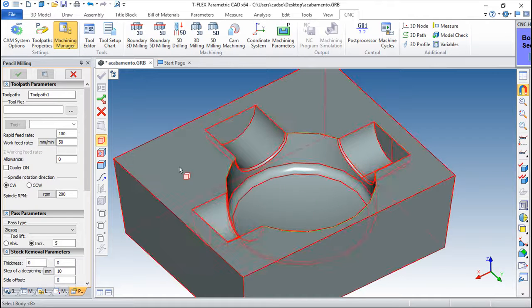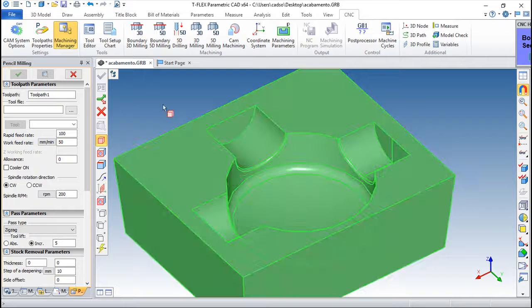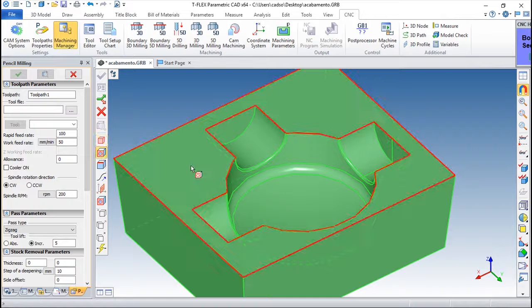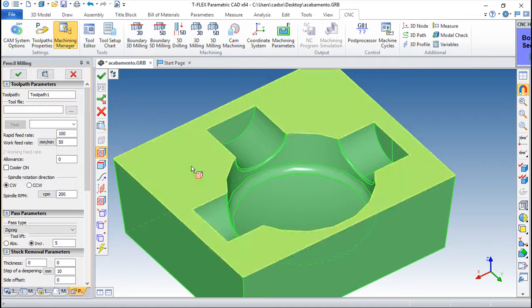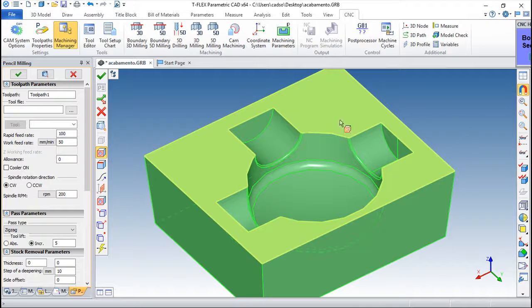So when we open the function, we can select several things, and the first one we can select is the full body. So I can pick my solid, simply this, and now I can choose from a face or an edge. For example, if I select a face, I can select this face here, and the limits of this face will be selected automatically for the machining.